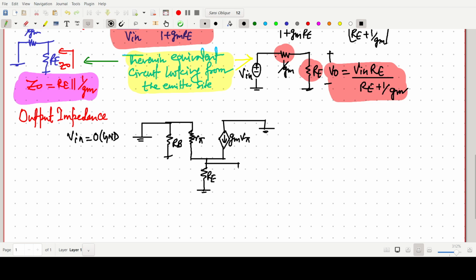And we are putting a voltage source, that is our VT, and some test current IT in the circuit, and this current is simply our IB, IC. Clear. So basically the impedance looking from this side is our Z naught.